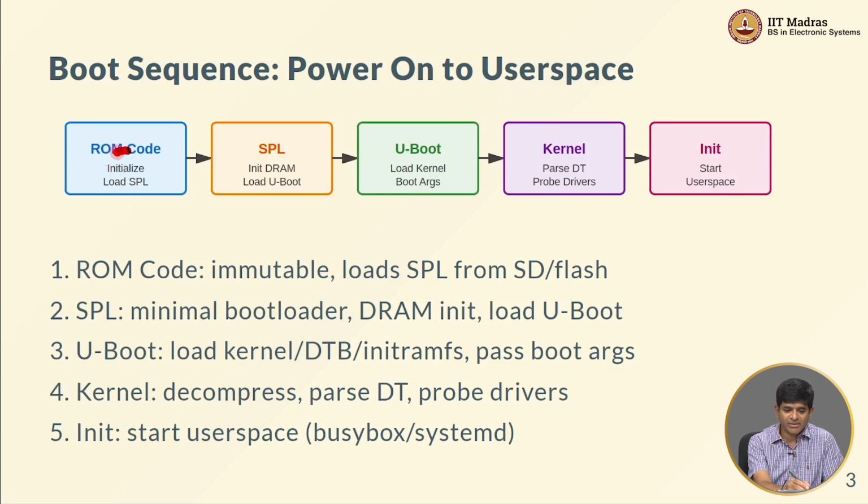It does some kind of initialization, and by initialization I mean not even things like disk or not even DRAM, which turns out to require fairly sophisticated initialization. The kind of initialization we are doing over here is for the registers or the chips that actually drive our power supplies and clock chips. Okay, so basically set up the clocks, set up the power supplies, right.